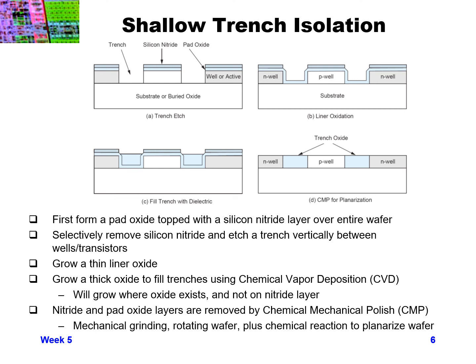Then we'll use basically patterning steps. So we'll use photomasks and photoresist to form patterns that expose only the areas where we want the trench etch. And so once we have gaps in the photoresist that expose the areas where we want the trenches, then we selectively remove the silicon nitride from just those areas where we want the trench.